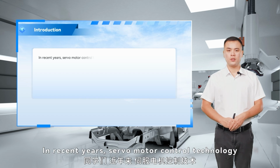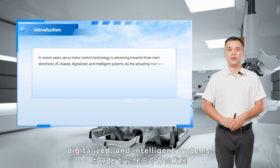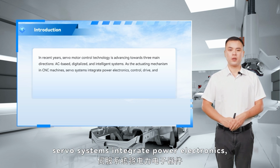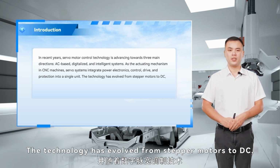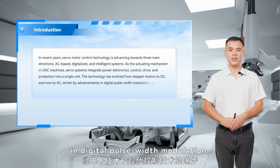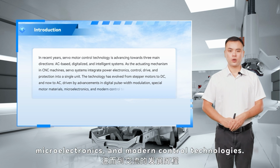In recent years, servo motor control technology is advancing towards three main directions: AC-based, digitalized, and intelligent systems. As the actuating mechanism in CNC machines, servo systems integrate power electronics, control, drive, and protection into a single unit. The technology has evolved from stepper motors to DC, and now to AC, driven by advancements in digital pulse width modulation, special motor materials, microelectronics, and modern control technologies.